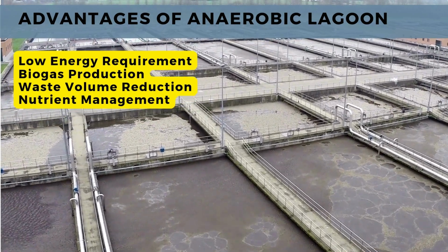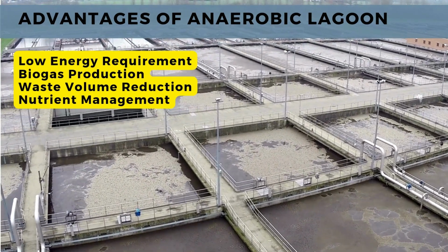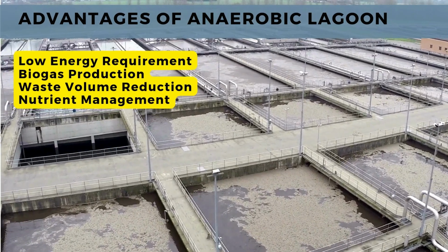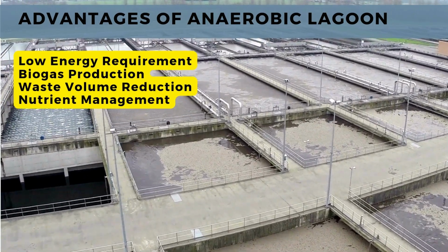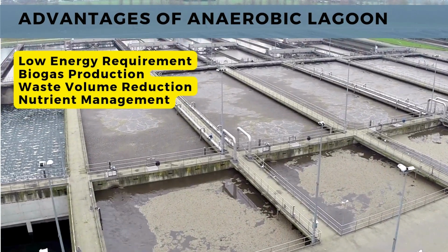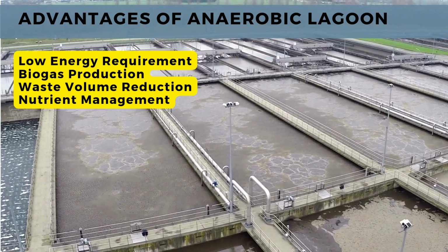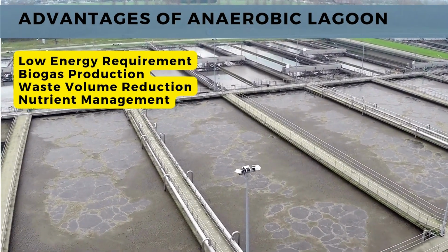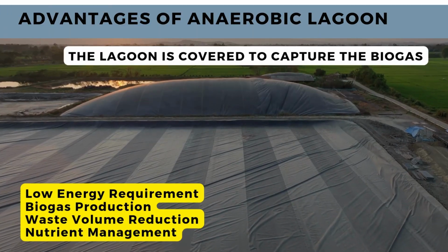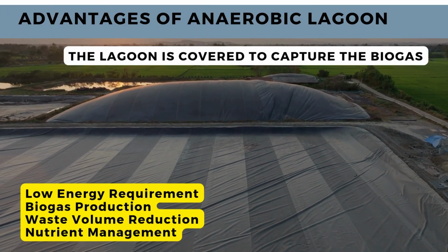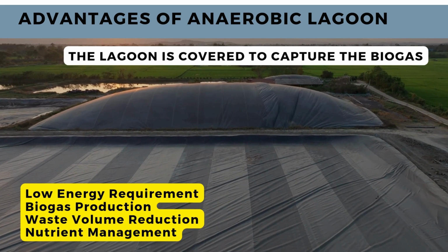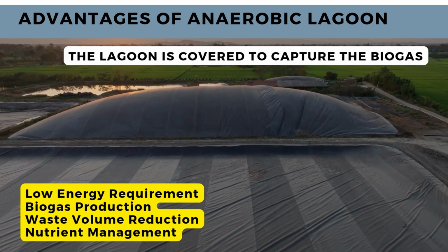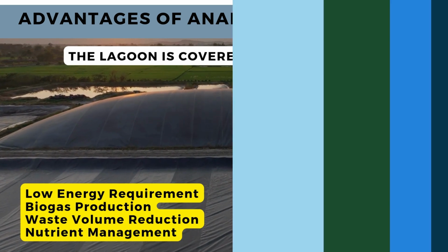These are the advantages of anaerobic lagoons. First, it has a low energy requirement. Anaerobic lagoons do not require mechanical aeration or constant maintenance, making them cost effective. It also produces biogas. Anaerobic lagoons produce methane, which can be captured and used as a renewable energy source.